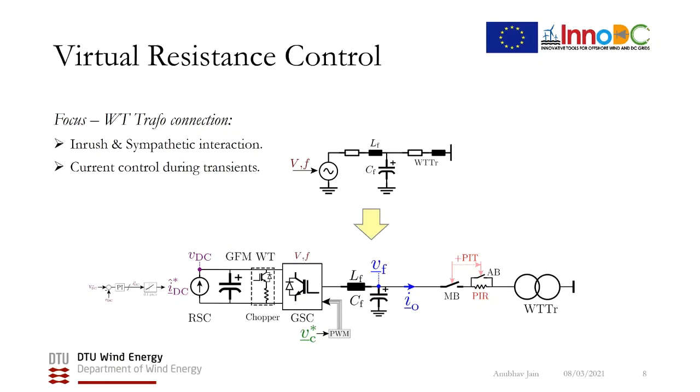So having studied the higher level target states in the energization sequence, focusing on the different grid forming control strategies and the major transients during energization of the offshore network and HVDC link, the next step, of course, involves looking inside the wind power plant and studying the startup transients of the wind turbines. Thus, we have added switching and transformer inrush details, as shown here, to the wind turbine model in the scope of studying the lower level target states.